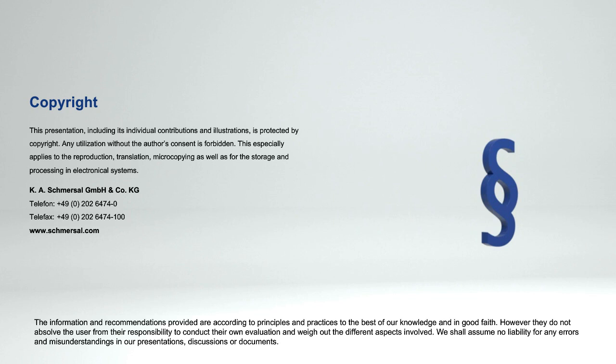So you look at, well, why would a key break to cause a single point of failure? When you look at the definition of Category 3 versus Category 4, for Category 3 you're supposed to detect as many of the single faults as possible, but you may not. And some of those may fall under fault exclusions. With Category 4, we can't do that. So we cannot have a key interlock switch for Category 4, but we can have it for Category 3.